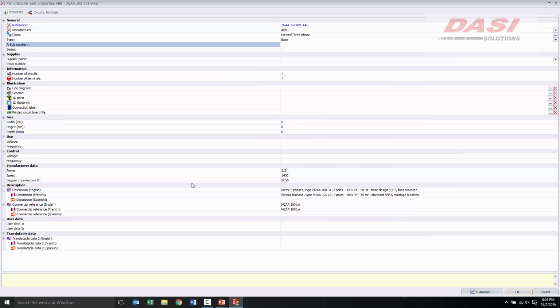Yeah, it can be. I just did a CIP one, and someone asked, "Can we fit it in a smaller box?" So I took all the stuff we had in the panel layout and tried to migrate it into a smaller box, and it looked like we had room to spare everywhere. Then I actually put it in the box and had to move everything around, because it would fit, but not quite. Some of the sizes were slightly off, and it ended up adding up.